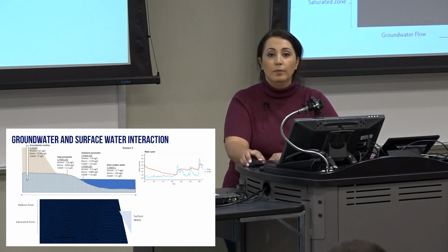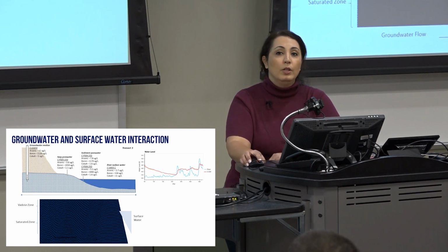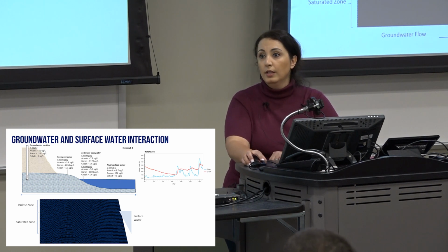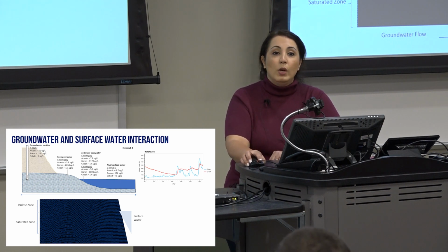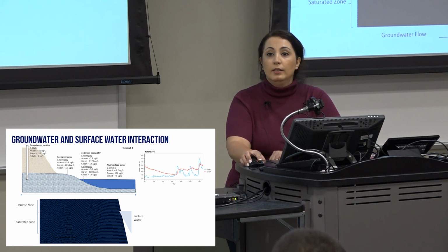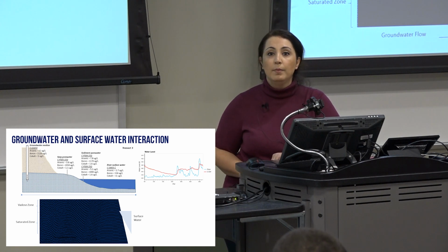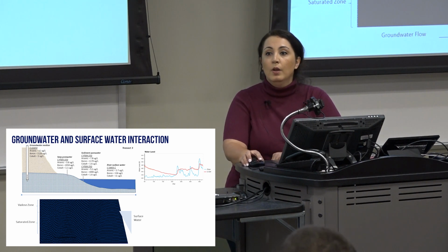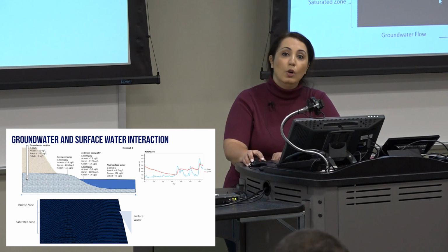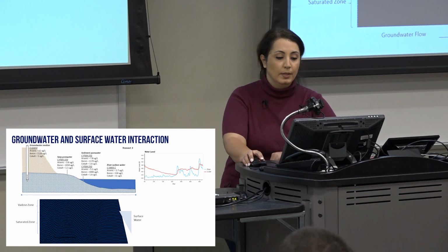We measured the concentration of arsenic, boron, cobalt in both locations, and we noticed that the arsenic concentration in the river is higher compared to the concentration of arsenic in the groundwater. The question that was raised was that during the year, with the fluctuations in the groundwater level and in the stream level, what will happen in terms of the chemistry in the groundwater? Will some of this contamination go to the groundwater when the river level is higher compared to the groundwater?